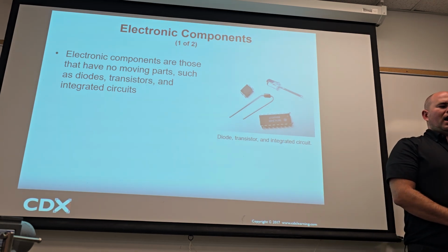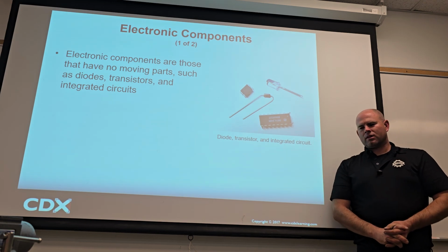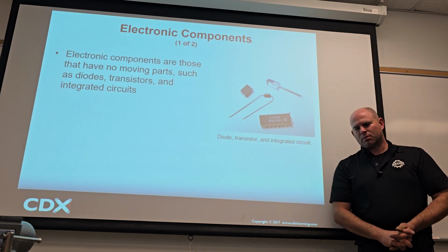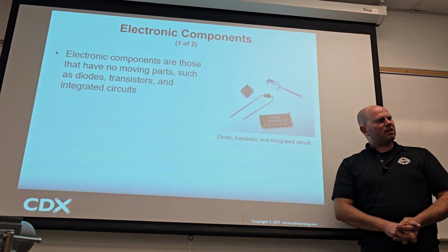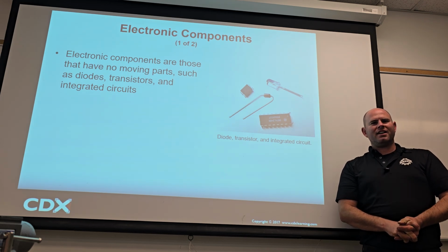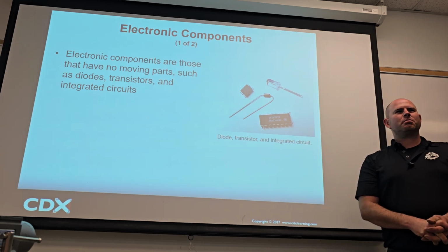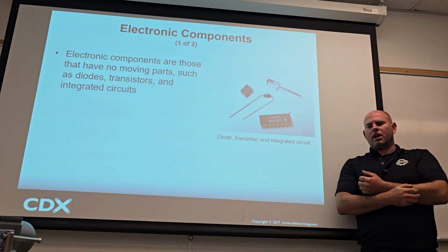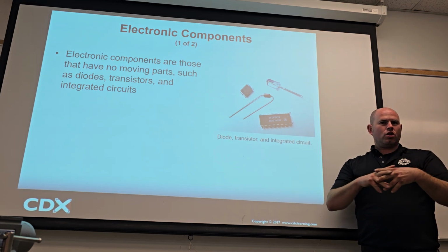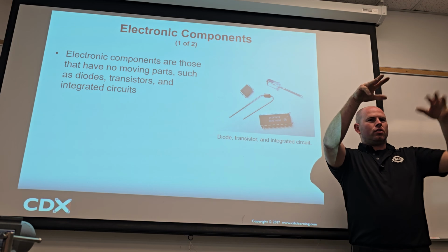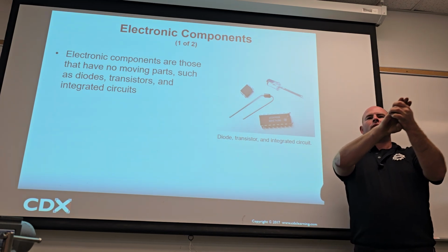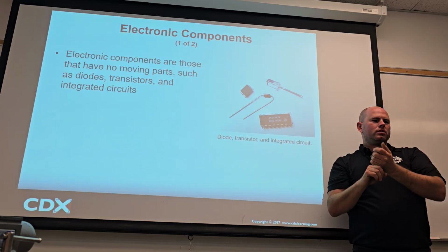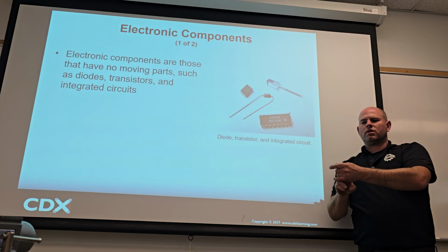So I can relate to that a little bit, because I actually have a crankshaft position sensor problem on my own vehicle right now. It's been a bit of a pain. It's my Hummer. It's always breaking down. It's broken down right now. But on a crankshaft position sensor, you've got the computer and 3 wires. One wire gives the sensor 12 volts. One wire gives the sensor ground.